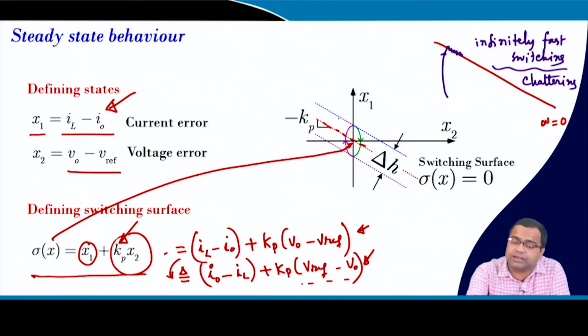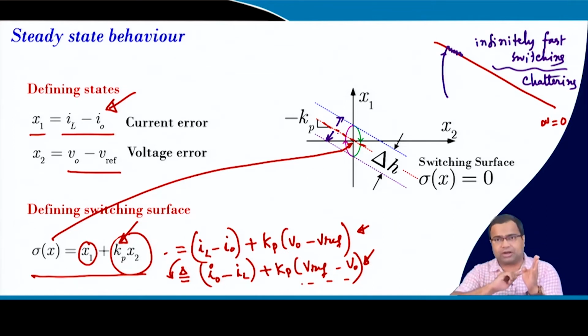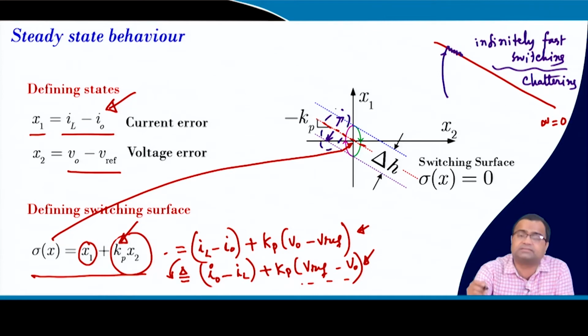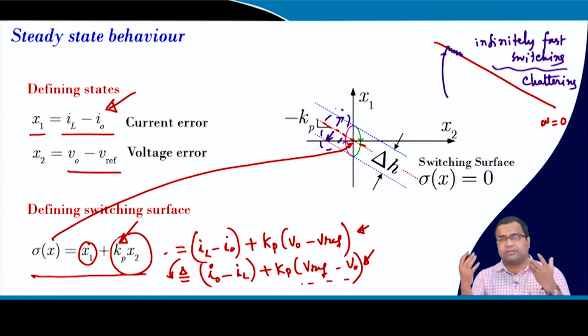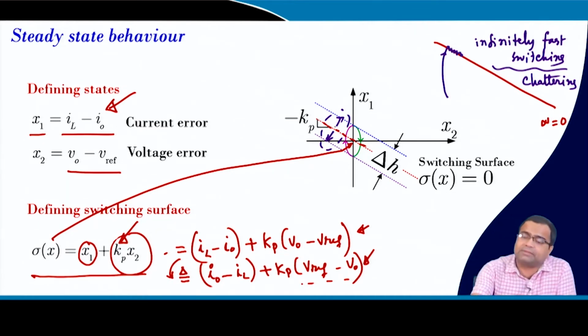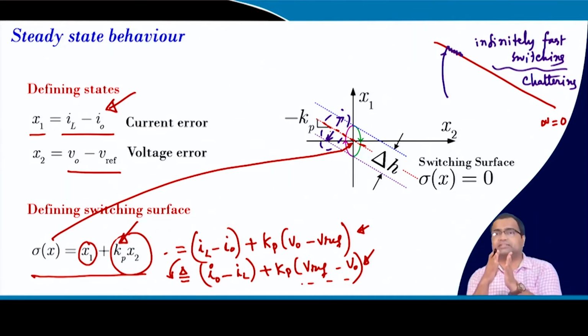That is why we need to incorporate a hysteresis band, which will introduce a dead time. That means once you turn off, you provide some time and then it turns on again. This can be implemented either by a direct time-based control, as we will discuss in a subsequent lecture, or directly on the trajectory by means of a variable, which is a hysteresis band.